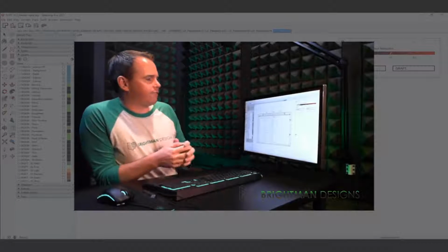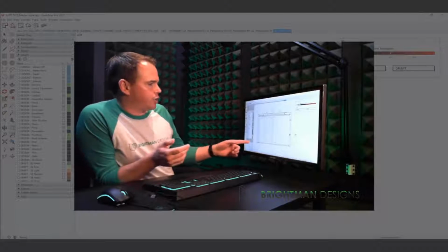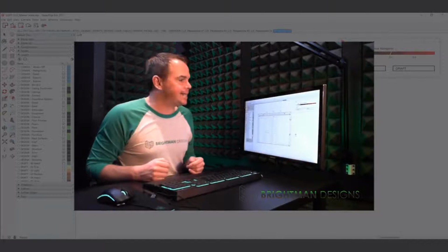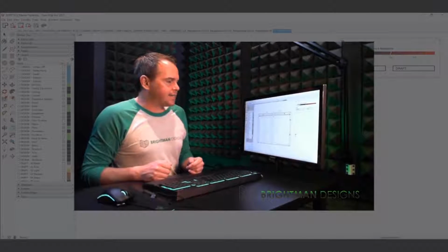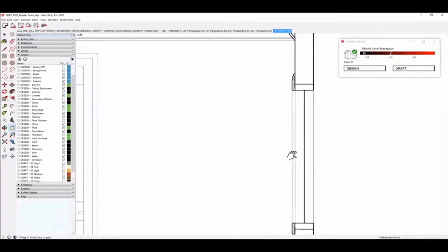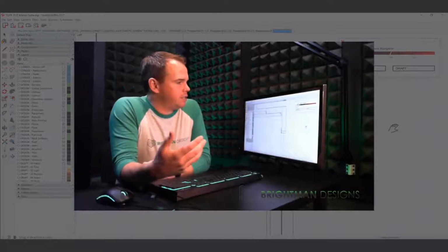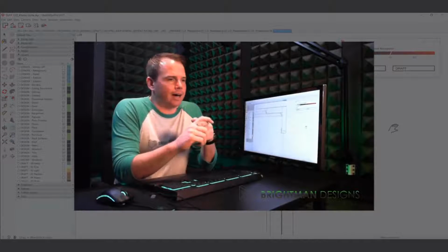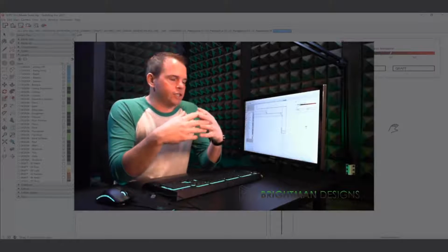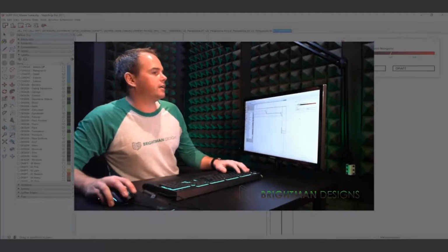We're not going to get hung up on fixing our section again, but right now our section is showing up with a really heavy black line where my section cut hits, and we've got just black edges. That's kind of what we're up to here. So let's just say I think you can get a pretty cool look out of these sections if the section cut is like 90% gray, and then the edges are going to be like 80% gray. So let's see what that looks like, all right?